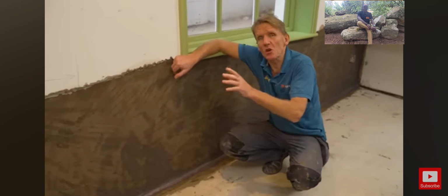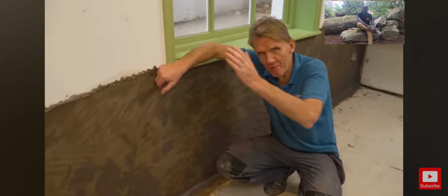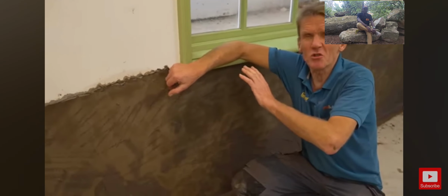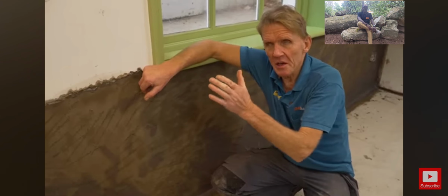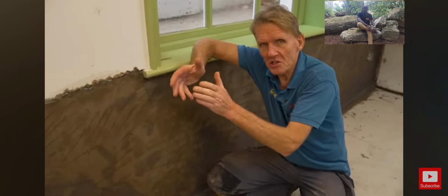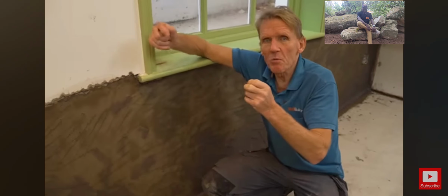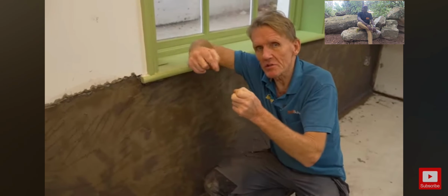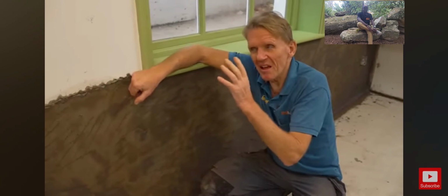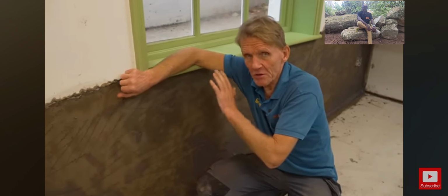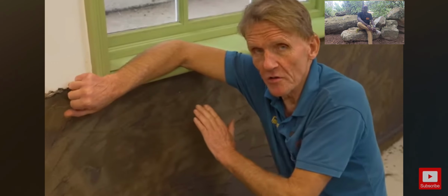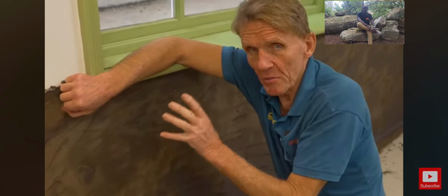Now, if you just tried to put this tanking slurry on rough bricks, or even some people try on painted surfaces, what you're doing there is you're not getting a flat surface to put the tanking slurry against. It's going in and out, it's got all kinds of little nooks and crannies. Now, when the water's pushing against it from the outside, that is likely, not definitely, but likely to fail. Whereas if you give it a proper flat surface to go onto, then it will adhere better.